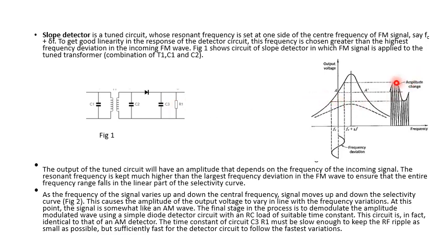In the portion where the amplitude falls to zero, the capacitor starts discharging across the resistor R1. Therefore, these RF fluctuations are smoothened out in the output of the circuit. So we will be getting only the envelope of the signal, or the actual message signal.